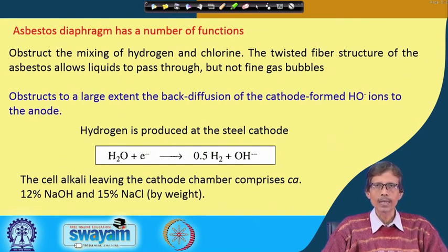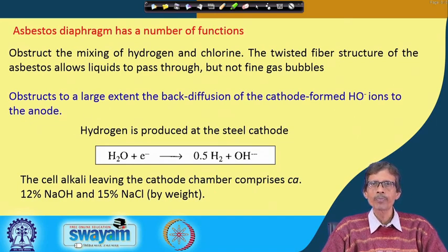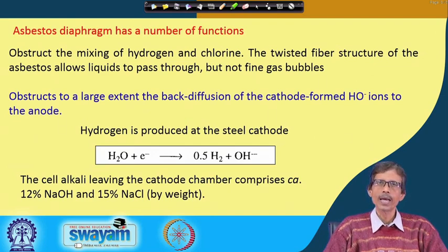The partial or selective crystallization of these two is possible, because when you take these two quantities out of solution they are solid. So, solid cakes of sodium hydroxide and solid cakes of sodium chloride can be produced from there, and you can separate these two, because fractional crystallization allows one of the materials to precipitate or crystallize before the other. So, the separation through crystallization is possible, and you get two solid products out of this reaction chamber.